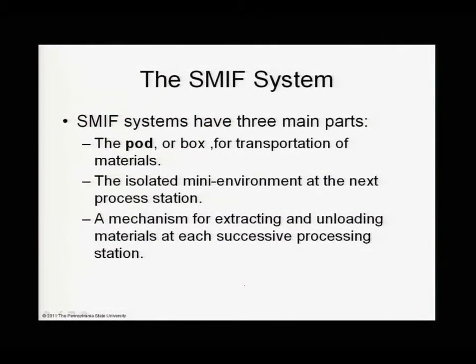So the SMIF box, or the SMIF system, has three main components. It has a pod or a box, hence that's why it's sometimes called the SMIF box, for the transportation of materials. And then you work in a mini environment that's very, very clean, and then you move to the next mini environment using the SMIF box.